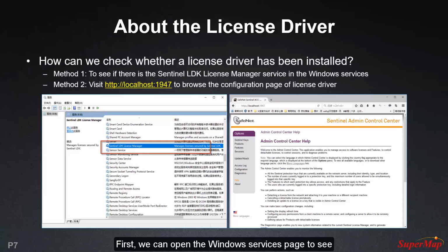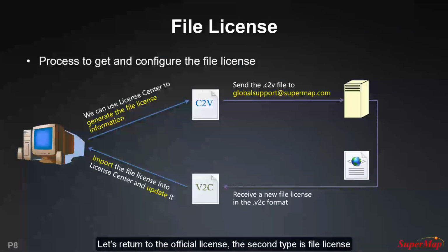First, we can open the Windows Services page to see if there is a service named Sentinel LDK License Manager. Also, we can point our browser to localhost:9047 to browse the configuration page of the license driver. Okay, let's return to the official license.